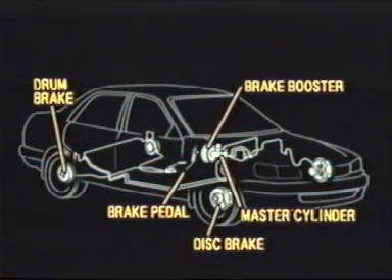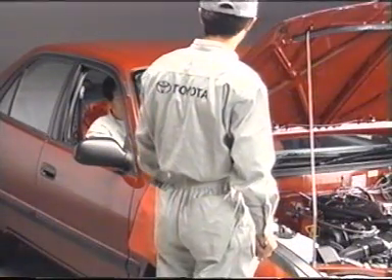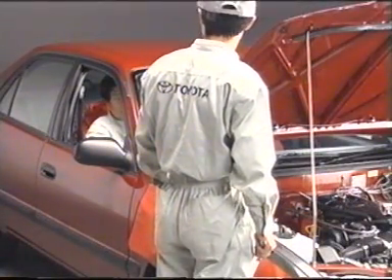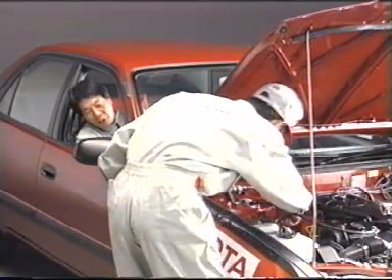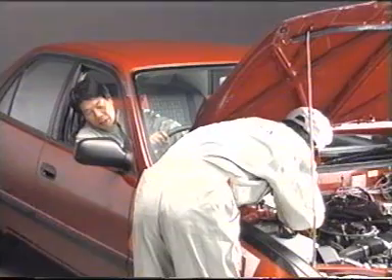If air is contained in the hydraulic circuits, the pedal feel becomes spongy. All air must be bled from the system whenever there is a possibility of air contained in the hydraulic circuit, or each time after disassembling the hydraulic circuit of the brake system.